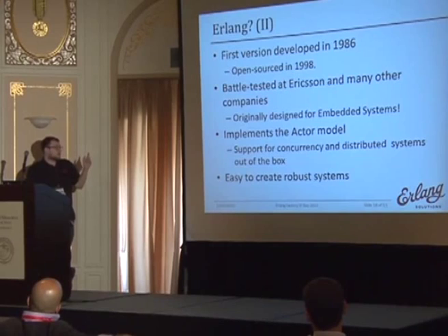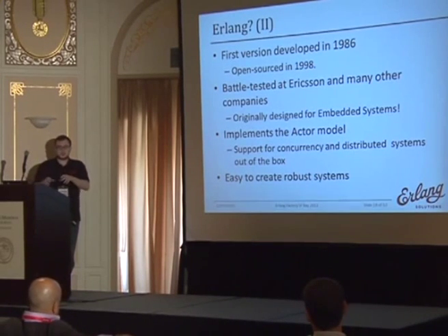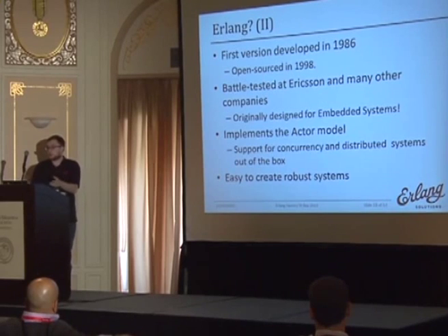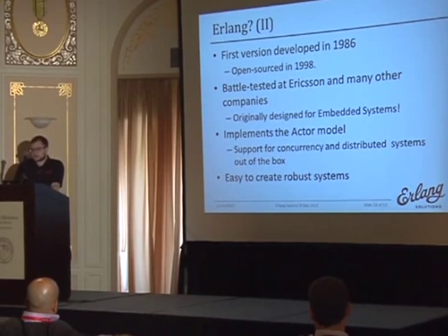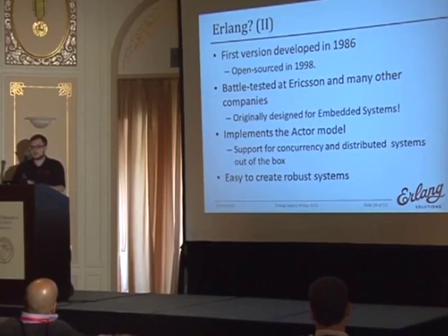It also implements the actor model, which lends itself very well to abstracting silicon. Silicon, by its nature, runs in parallel. Each individual function that you have on your system-on-chip device is independent from the rest of the system. You do have to, from time to time, communicate between those blocks, but really, you can architect or model your system-on-chip using a set of Erlang processes, actors, really nicely.